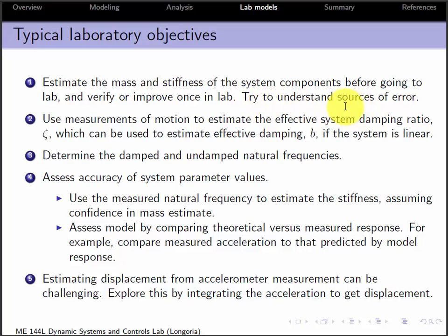And you can try to understand where my equations for stiffness or my estimates of mass might be off. That's something we're trying to show you with this lab. Remember, the value of that is if you're ever designing some kind of system where you have to take into account its resonance and you're making decisions on mass and structural design, you can see here how well some of these basic equations might work for predicting what those resonances might be.